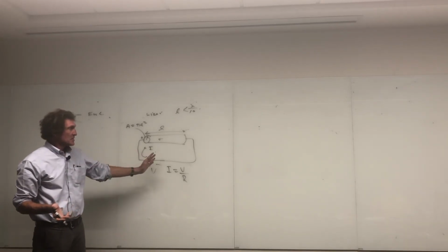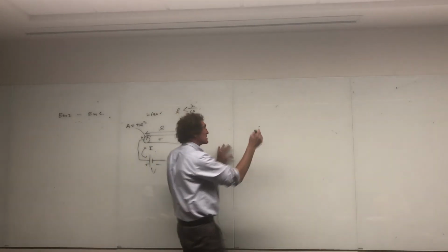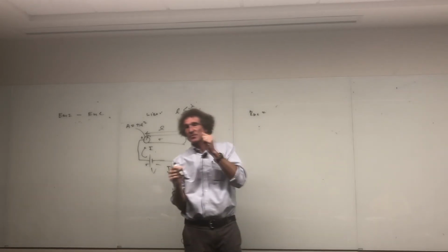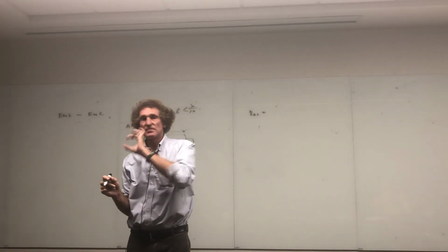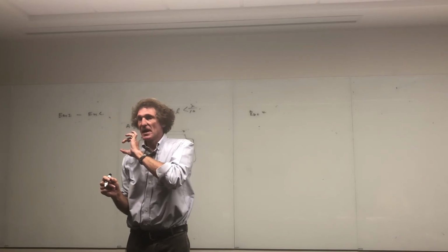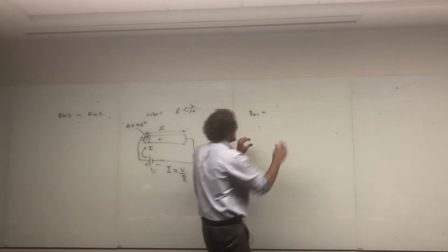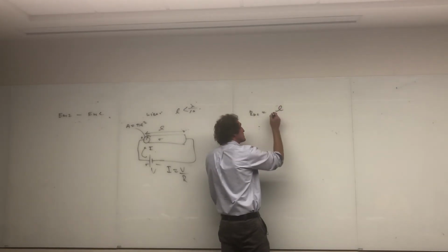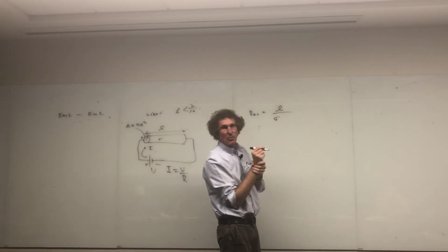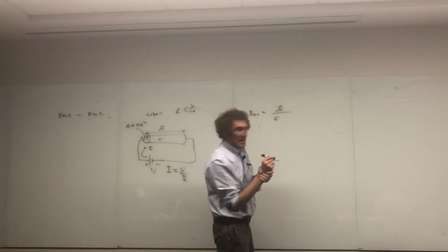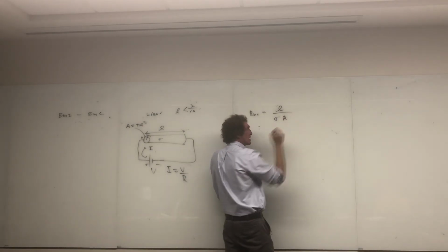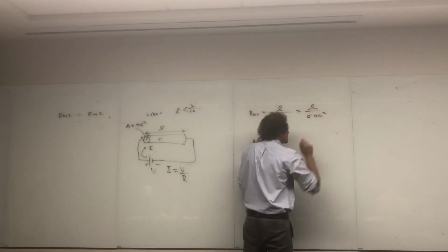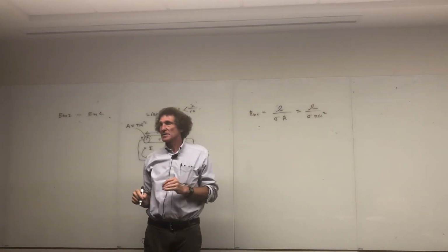So when we look at this, we talk about something called the DC resistance, or R_DC of this wire. Now the key to this thing is twofold. First, the cross-section of this wire does not change at all. Constant cross-section, and this is at DC. Well, R_DC is always proportional to the length of the wire. Most of you know this, right? It's inversely proportional to the conductivity. The more conducting a wire is, the lower the resistance for a given length. And it's inversely proportional to the cross-sectional area. That means it's L over sigma pi a squared for a typical round wire. A is the radius of the wire.